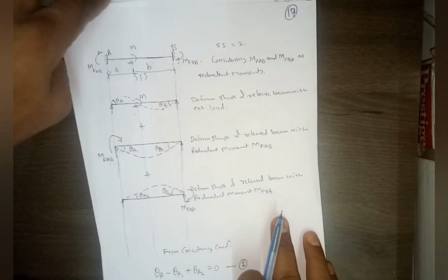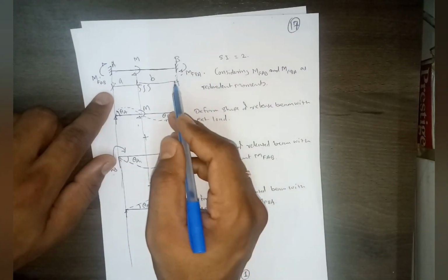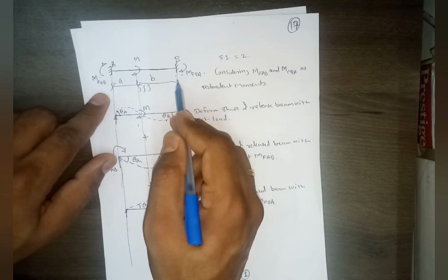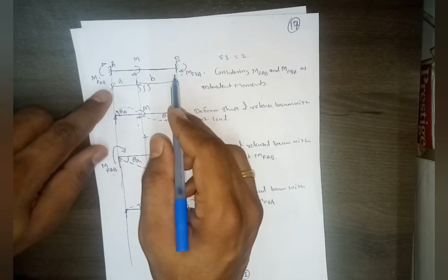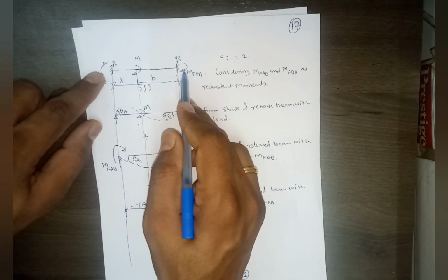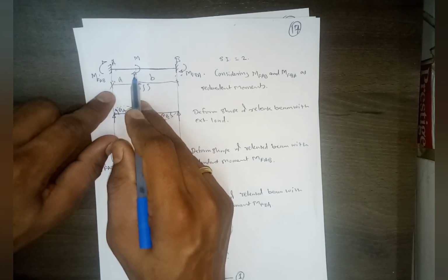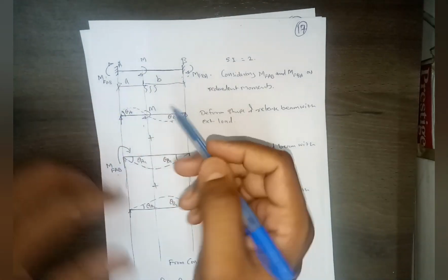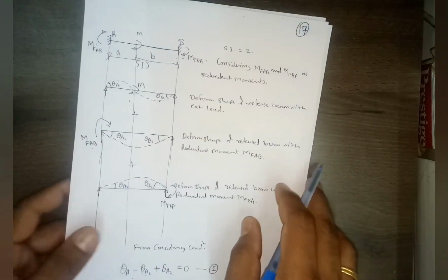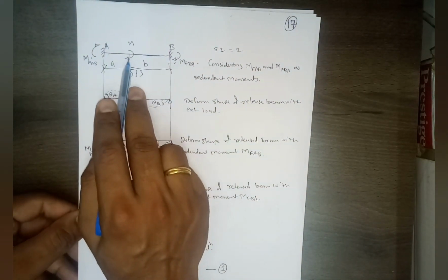So we have already discussed that calculating shear force is as normal as a normal problem, but for calculating bending moment, what we do, we plot the bending moment due to this fixed end separately, and then because of this load we plot separately, and then we overlap, right? So anyway, we'll solve some numericals at that time. We'll see how we can plot the shear force and bending moment diagram.